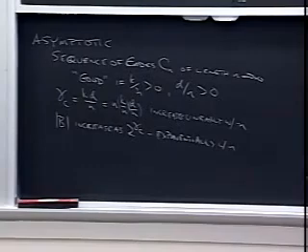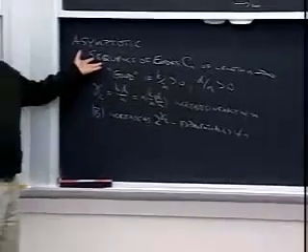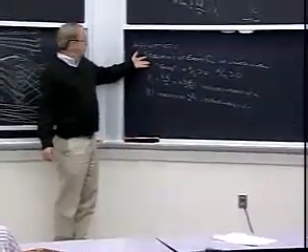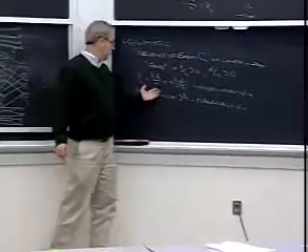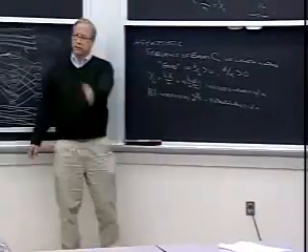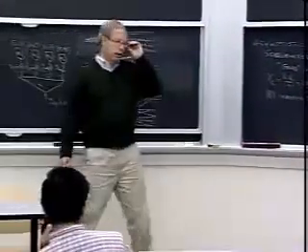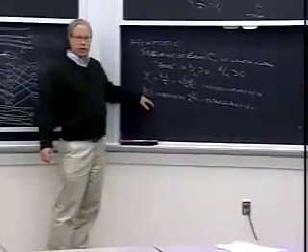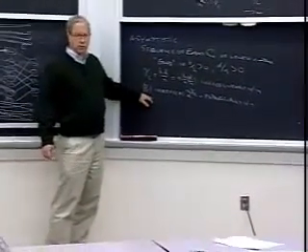So basically what this says is that if your objective is to get a good sequence of codes, if this is the way you think you're going to get to channel capacity, then sure enough, your nominal coding gain will go up to infinity linearly with n. But how are you going to decode it? Our first method was simply maximum likelihood decoding.